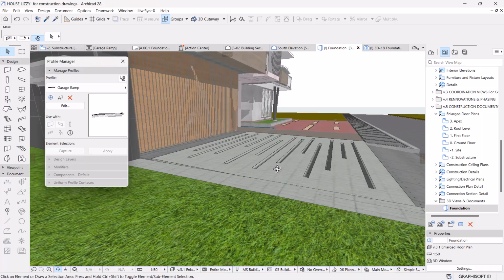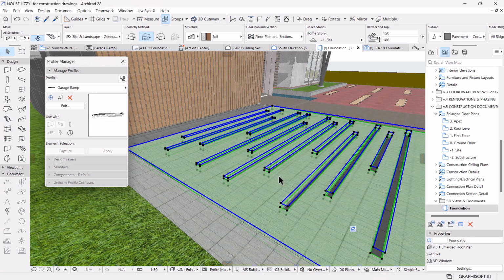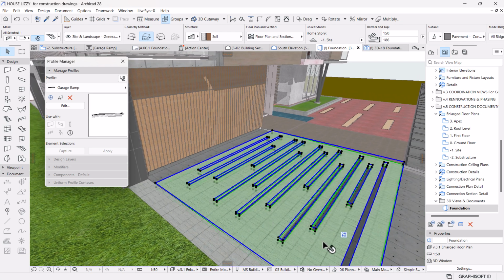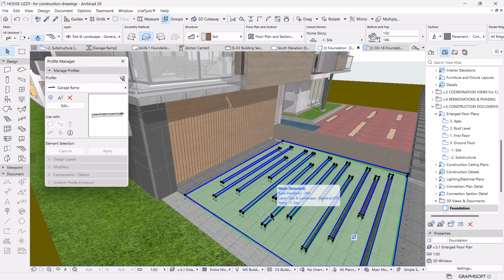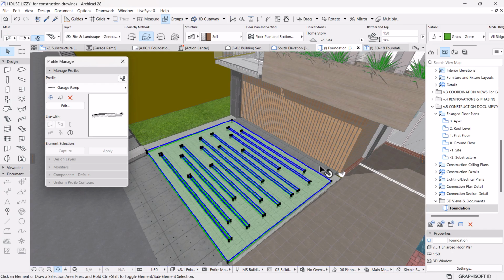We had this initially. This should be the patches of our grass, and the only way to achieve this during construction is, when we're casting concrete, we need to make provision for this hole so that we can fill in with soil and grass. How do I now transfer this information to our newly created ramp?